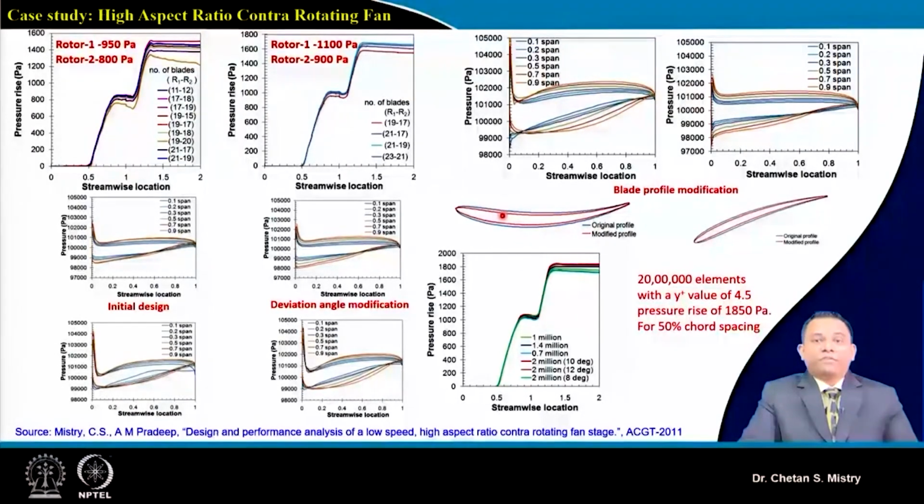Later on we modified it by shifting the maximum thickness point as well as reducing the thickness of this aerofoil, and by doing so we were able to achieve the pressure rise as per our expectation. So by having this kind of initial study, this initial analysis, we get confidence about the design. Again let me put this point here, this CFD is not a design tool,